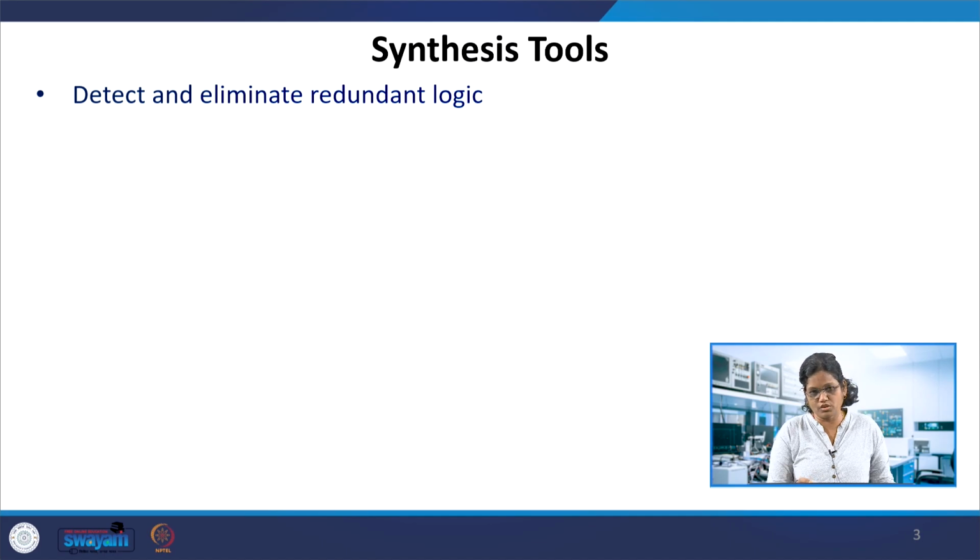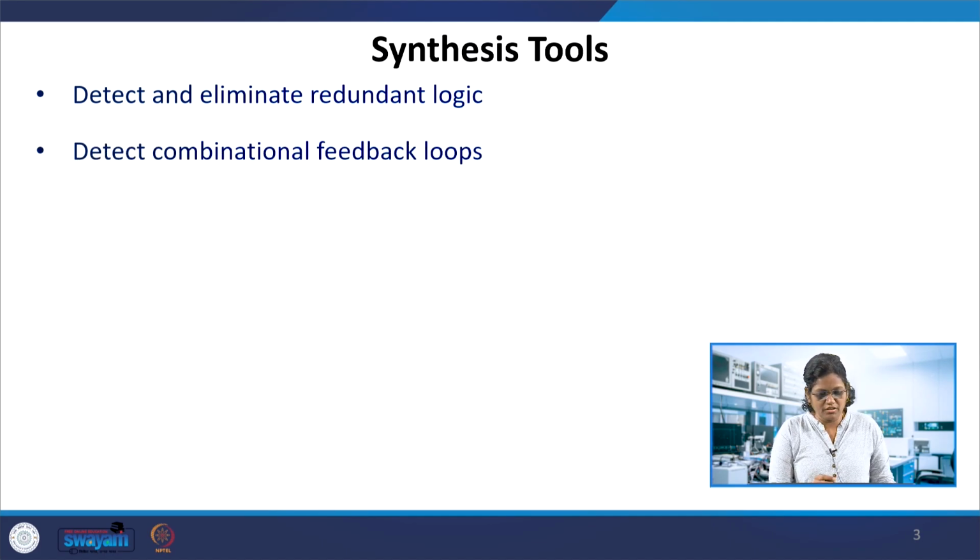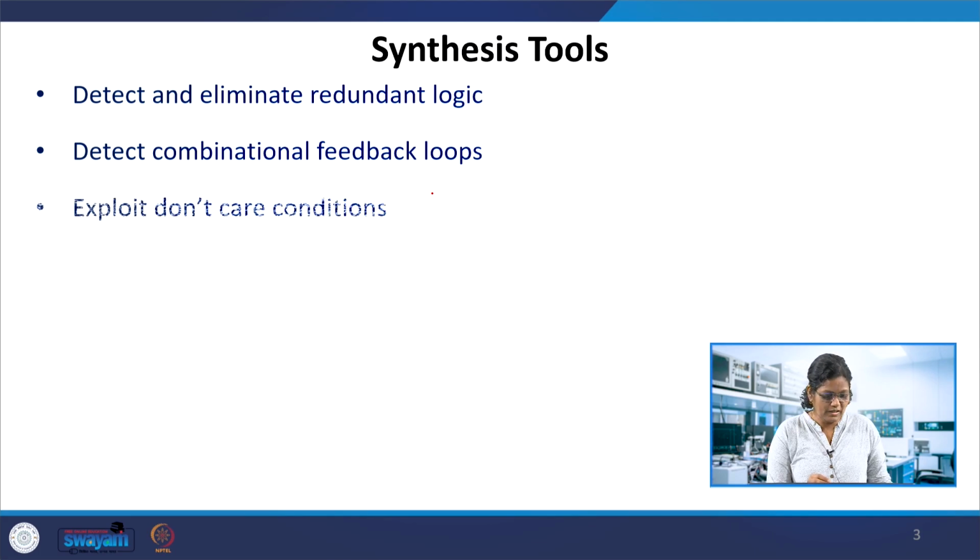If there is any logic which is redundant or needs to be omitted, it is removed. It also finds any feedback loops in the combinational logic. Feedback loops are allowed in sequential circuits, whereas in combinational logic, any feedback loops need to be dealt with differently, or it exploits the don't care conditions.